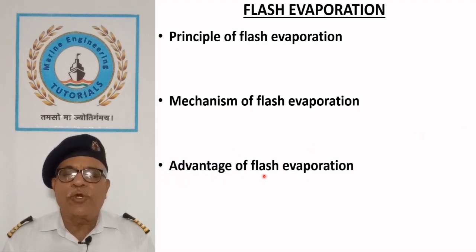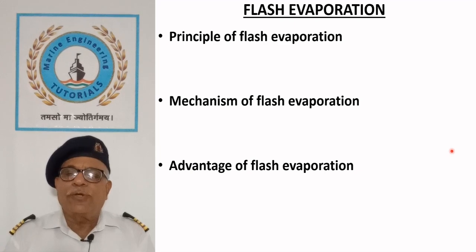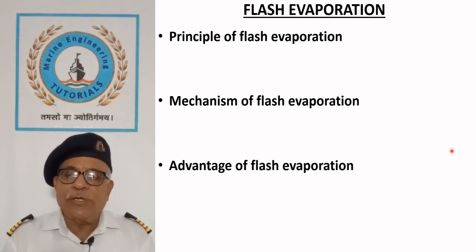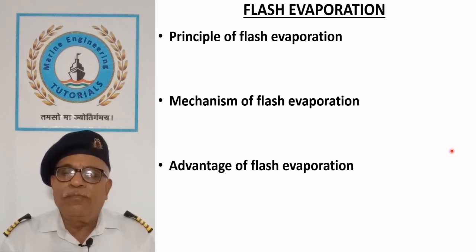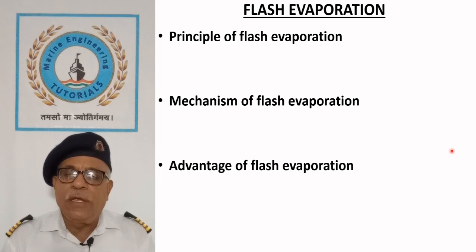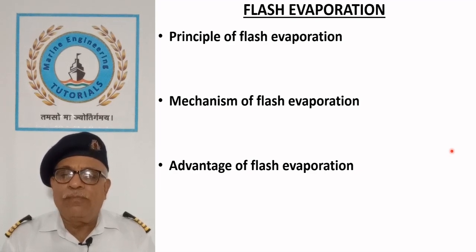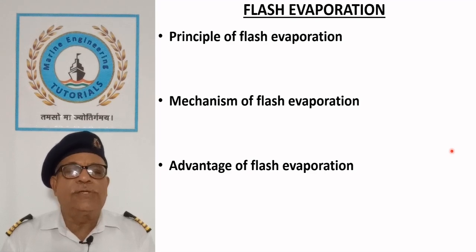Advantage of flash evaporation. Flash evaporation helps in utilization of waste heat of engine cooling water having temperature below 100 degree centigrade for boiling seawater, which improves plant performance. Evaporated seawater contains negligible salts, which is absolutely necessary for use as boiler feed water or engine cooling water to prevent corrosion and scale or sludge formation in these systems.